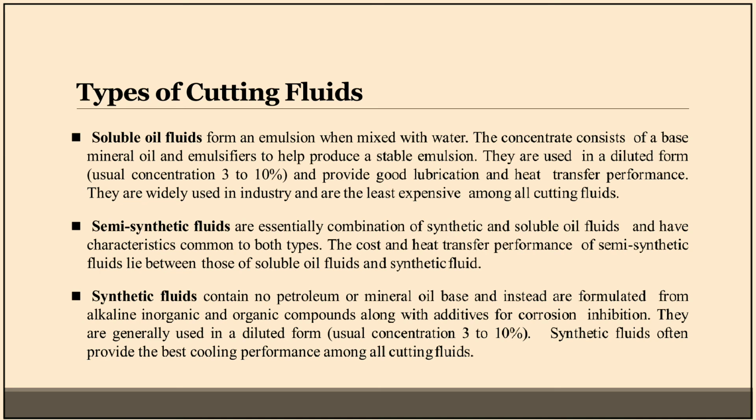Synthetic fluids contain no petroleum or mineral oil base and instead are formulated from alkaline, inorganic and organic compounds along with additives for corrosion inhibition. They are generally used in a diluted form, usual concentration 3 to 10%. Synthetic fluids often provide the best cooling performance among all cutting fluids.